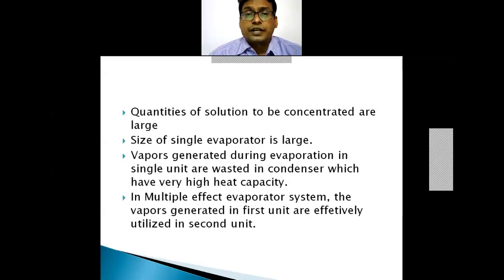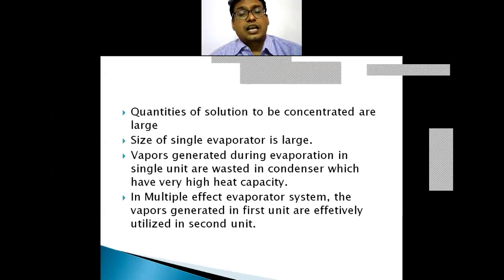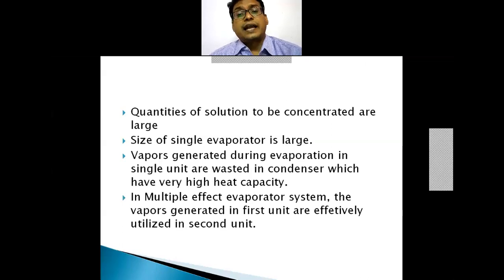Where the quantities of solution to be concentrated are large, we use multiple effect evaporators. As the quantities are large, the size of a single evaporator would be huge. From the point of view of reduction in fabrication cost, equipment cost, and handling cost, all those costs will be reduced, and so multiple effect evaporator systems are used.